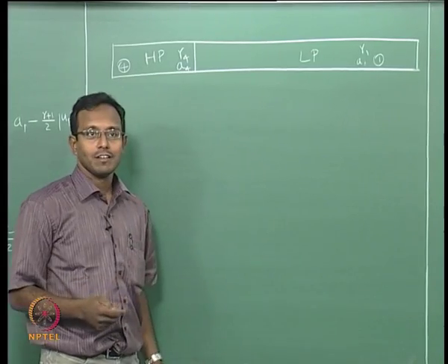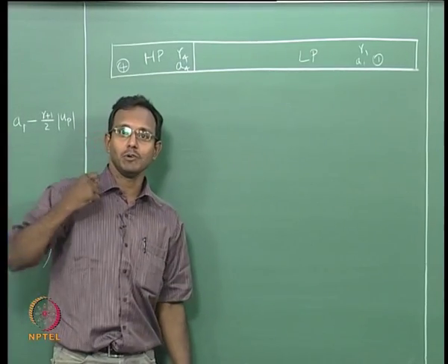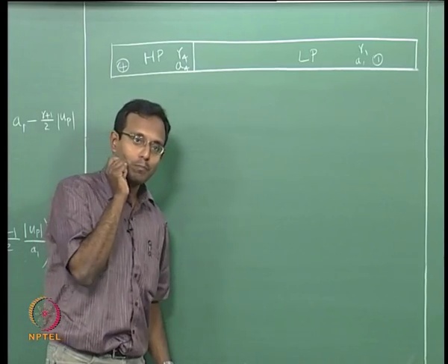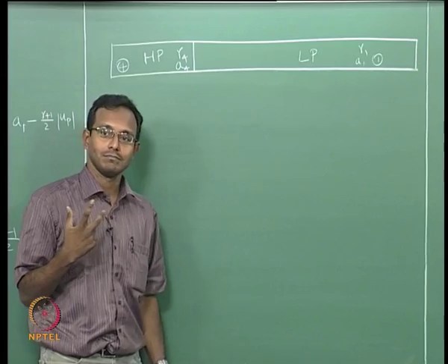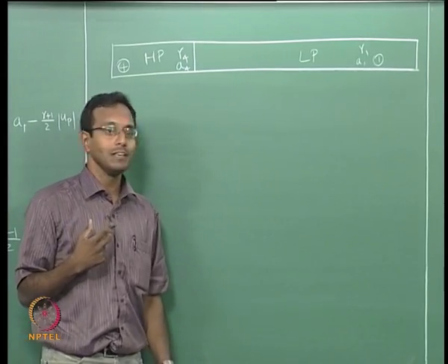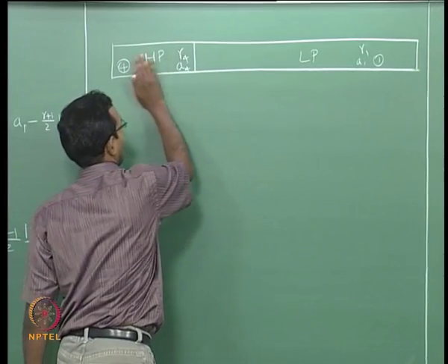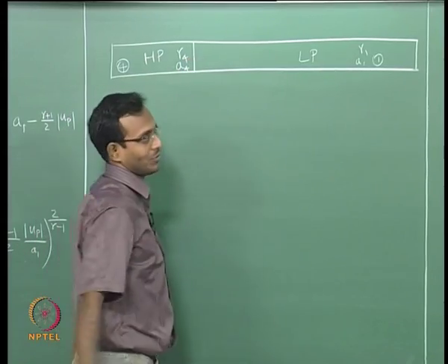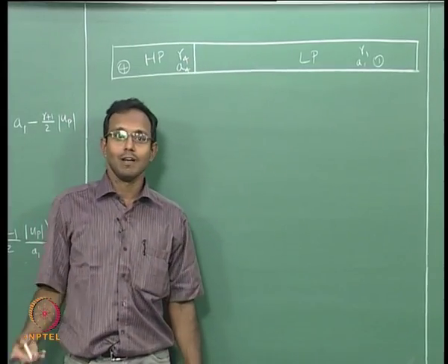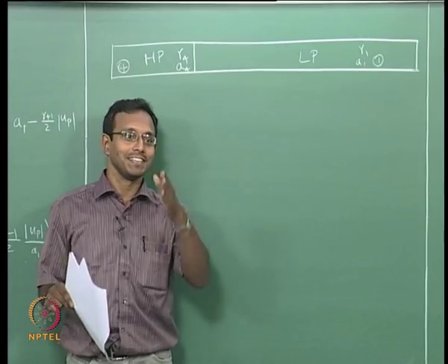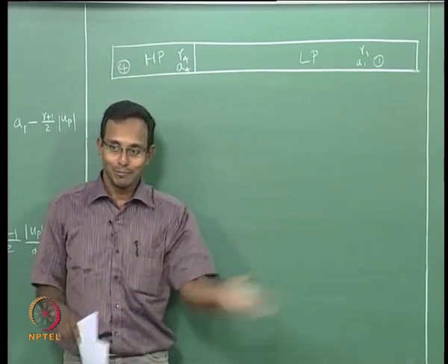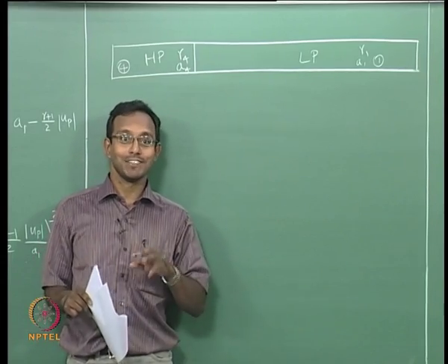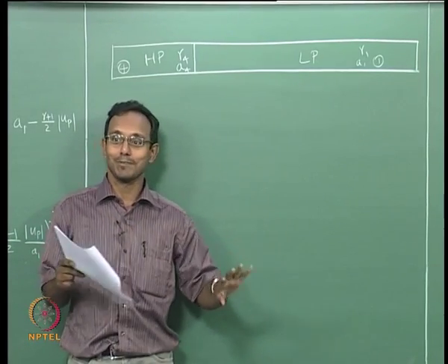That is what I have, and I am going to say at time t equal to 0, I am going to puncture this diaphragm. Somehow I make it crack, there is no more diaphragm. Suddenly the high pressure section of the gas meets the low pressure section of the gas. What will happen? It is like opening the gate at the stadium which is crowded and the outside there is nobody. There is going to be a whole set of people running out, and an expansion wave travels into the stadium. We already talked about this problem.